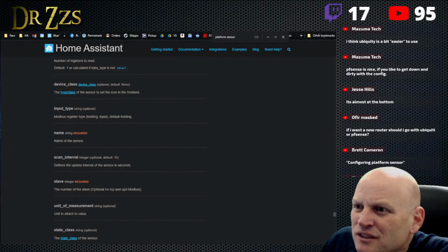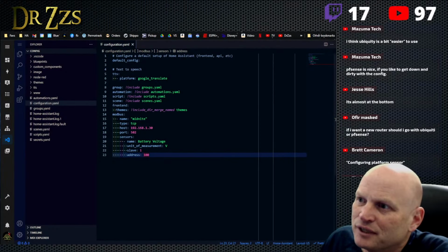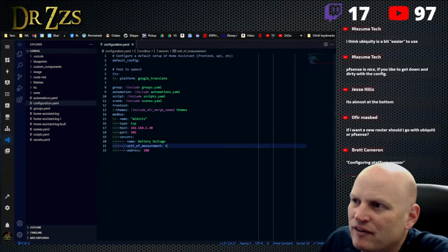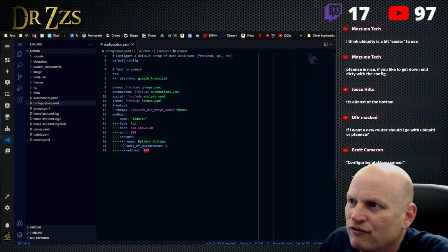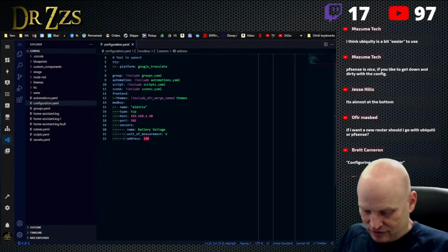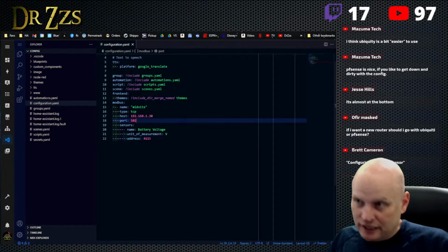The number of the slave, optional for TCP and UDP Modbus. It's optional, right? Whatever. Let's just take it out. And then the address you said was 4115. Okay. Let's try it.